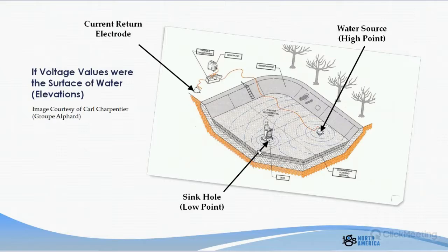And if you have a leak in the survey area, you have a point where the water is exiting. It's a lot like taking the drain plug out of a bathtub, and then you get a funnel of water going into the hole. That's exactly what the voltage field does. And so the current is exiting the hole from all directions. And we walk around the survey area with this dipole. In the figure, you see a little guy with a double dipole. He's got a dipole on the left and the right, just to be more efficient.